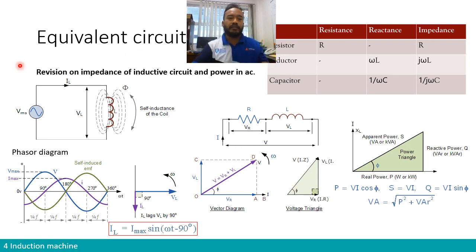Right. So to do that, the equivalent circuit that we're going to study is, of course, an equivalent circuit that has certain impedance components, especially inductors, right? So it is not only a resistive circuit with only resistors. It will involve inductors, because an electrical machine is basically just a coil, a combination of coils, so they have inductance and therefore impedance.